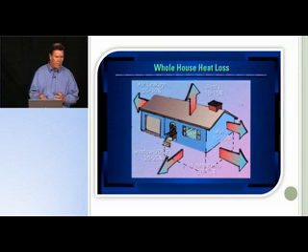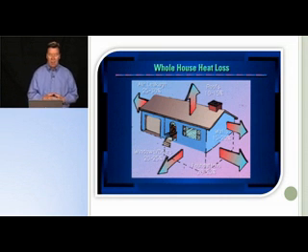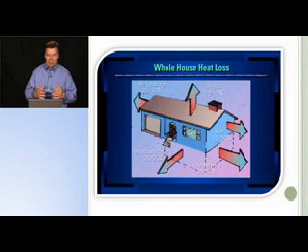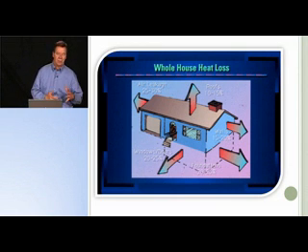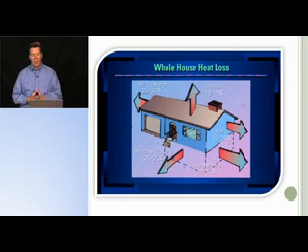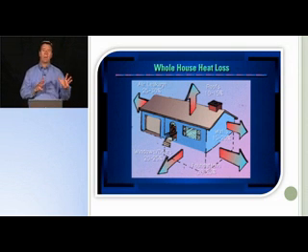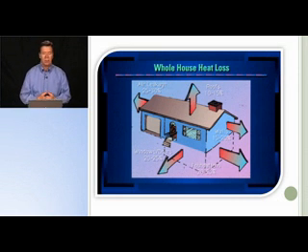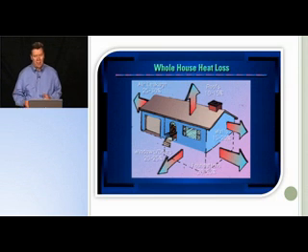When we talk about air infiltration, what we're really referring to is air that tends to be blowing in through the wind through all the cracks and gaps. When we talk about other types of heat loss, for example, the roofs or attic area loses about 10 to 15%, about 20 to 25% through doors and windows, 20 to 25% through foundations, and 15 to 20% through walls. Now, every home is different. That's why it's important to recognize that these are not hard and fast numbers, but as a general rule, that's how the heat is lost and gained out of homes.